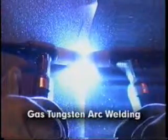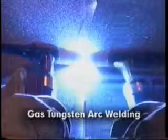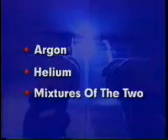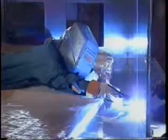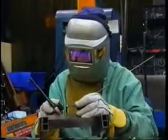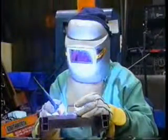Gas tungsten arc welding uses a non-consumable tungsten electrode and externally supplied inert gas shielding. The most common shielding gases used are argon and helium, and mixtures of the two gases. All types of steels and most non-ferrous metals can be welded in all kinds of joints and positions. Depending on the application, workpieces can be welded without a filler metal or welded with a filler metal supplied separately to the joint.